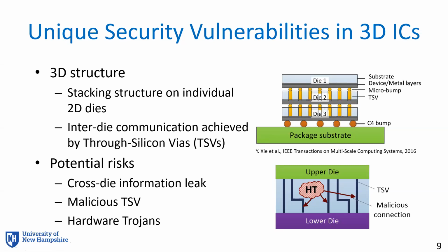So the potential risk, which is also unique to 3D ICs, is that we now need to consider malicious vertical connections and more hardware Trojans, which have much more complicated trigger and payload architectures in the 3D system, as well as cross-die information leak.